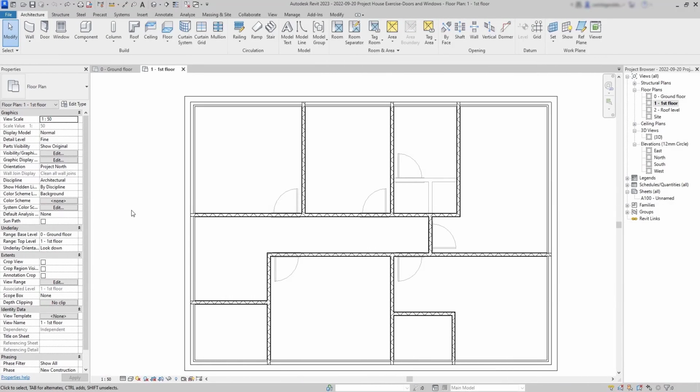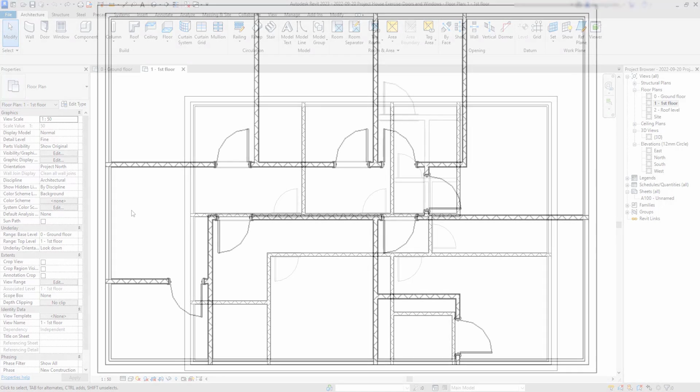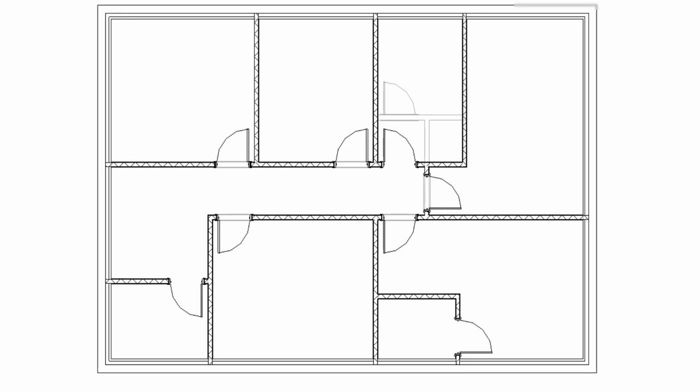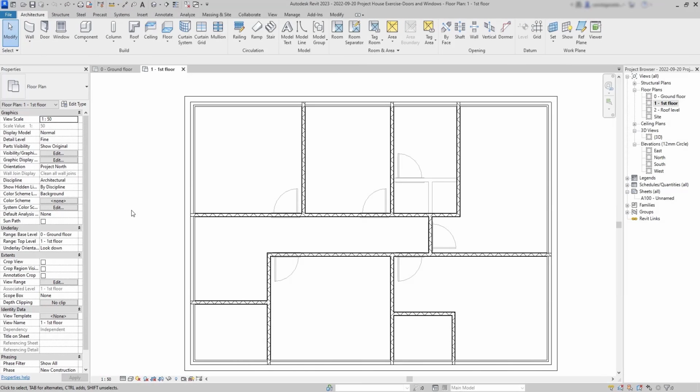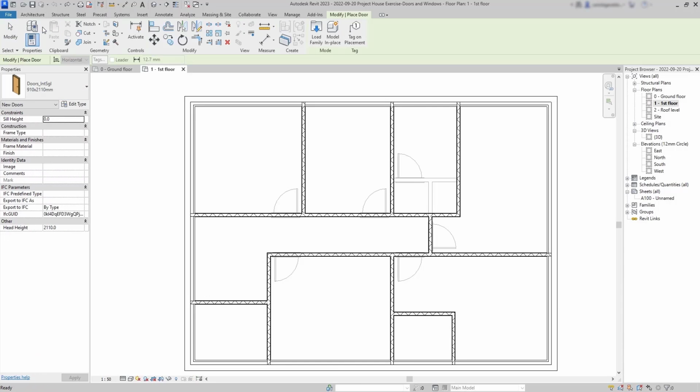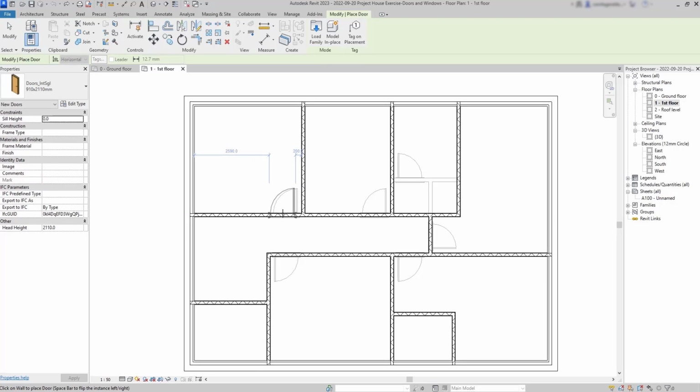Now let's switch to the first floor, and as there are still remaining doors here, I encourage you to draw them by yourself, but if you wish, you can follow my suggestion that I show to you in this plan. So this is actually easy. Just follow the same process, and as some of the doors are exactly in the same place as in the floor below, just go to the shadow and make sure the distance to the wall is the same as the floor below.